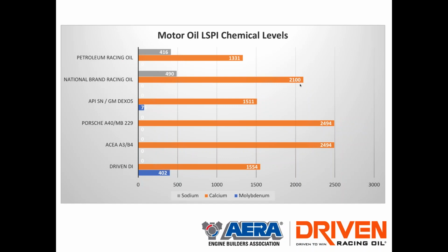And when you look at the oils that are on the market today, a lot of the oils out there are higher calcium oils, because that's been the detergent of preference. And with going towards longer and longer drain intervals, you typically can achieve that by boosting the antioxidancy package and by boosting the detergent package and the traditional detergent everybody uses, calcium.